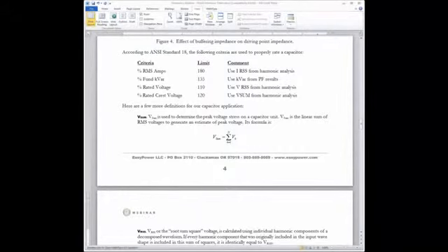One other very important thing: when you start applying power factor correction, which basically a notch harmonic filter is, it's a combination of power factor correction and filtering. What you're going to find is your voltage is going to go up. And so if your voltage goes up, you have to make sure that the size and the amount of power factor correction you're putting in there doesn't cause you to go into some form of an overvoltage condition. So make sure that you run power flow cases as well, and you'll see that with one of my examples that I have here.